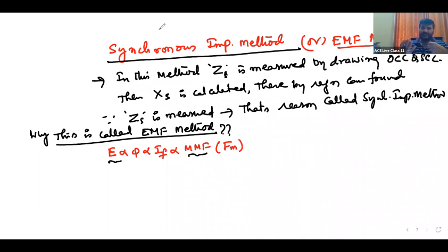The leakage reactance drop means what? When current is flowing, flux links with the conductor and an EMF is induced, a statically induced EMF. That induced EMF opposes the actual generated EMF, thereby the net voltage decreases. So leakage reactance is an EMF phenomenon that can be represented with an EMF vector.